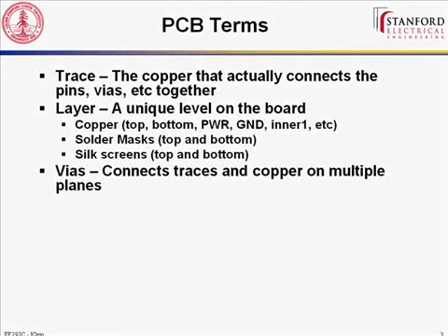There are also things called blind vias and buried vias, which only go between certain layers and don't connect all the way through your circuit board, but that makes your boards a lot more expensive and a lot harder to fab. So unless you're doing high-end consumer electronics, you won't be using blind or buried vias anytime soon. But they do exist.